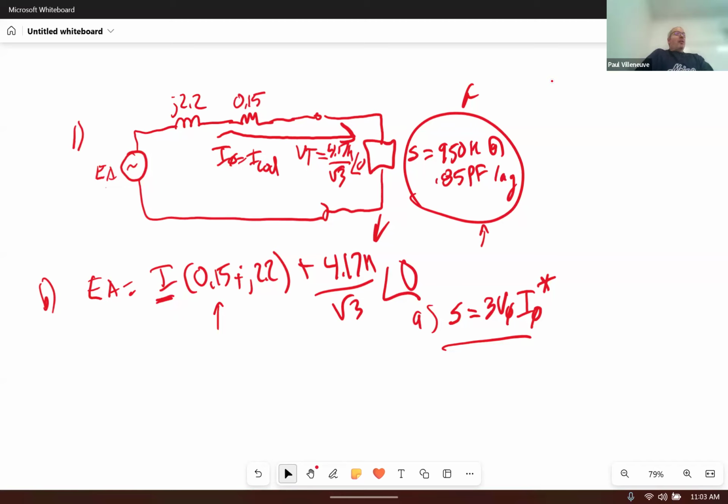Because in the real world, a lot of times you're going to be given a load at a certain MVA or KVA rating at a certain power factor. You should be able to calculate the current, right? That's the known that you have. The utility tells you the load is 1,000 MVA at a 0.9 lagging power factor. If I give you a nominal voltage of the system, you should be able to pretty accurately calculate what the current is. Okay? That was problem one's question on problem one.